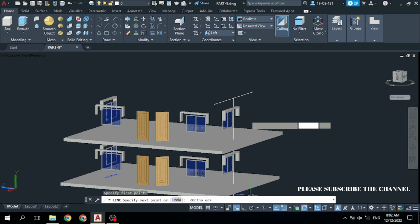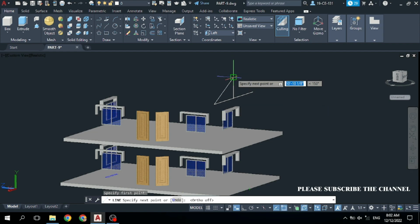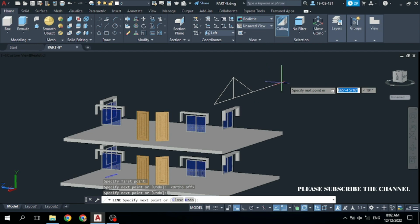Ortho must be on and type 5 feet distance upward. Type 5 feet and press enter, and then again enter. Then click on line command and start your line from this end point, and then ortho off and click it at this point, and then click it this point and press enter,